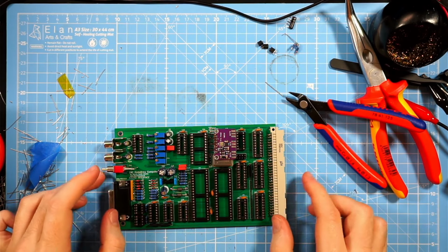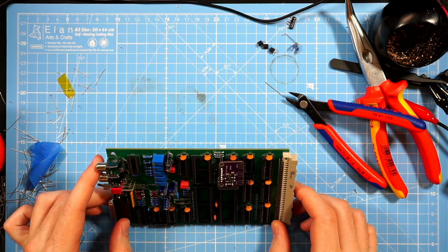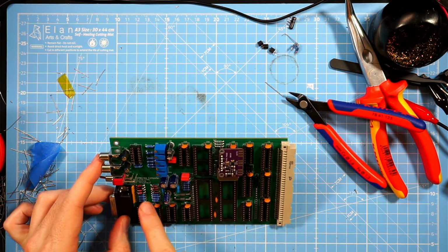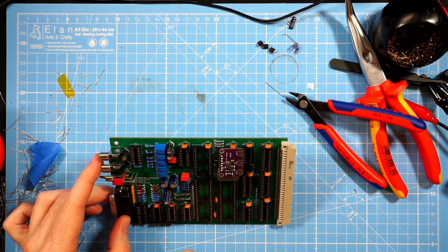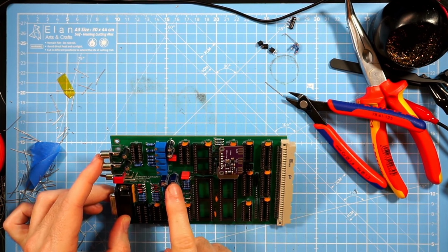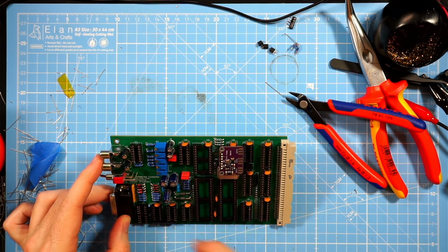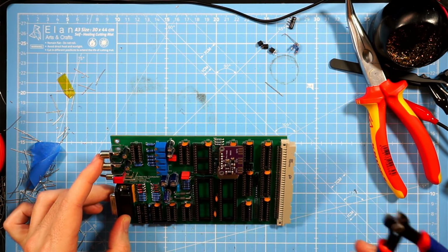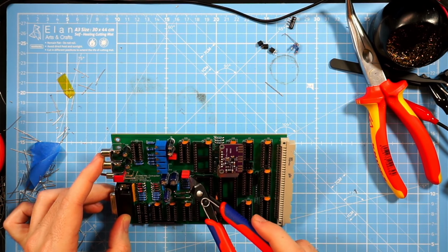It's done. It's been a few hours, and it was quite a lot of work to solder all those components and sockets to the board. I struggled, for example, with the diodes because I chose the wrong footprint again. I swapped some parts around. For example, these two capacitors are a bit smaller than specified, and those are a bit bigger, and that shouldn't be an issue. It's just that those 2.2 nanofarad capacitors that I originally chose have this footprint, and they won't fit here.